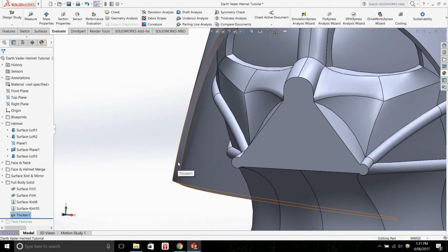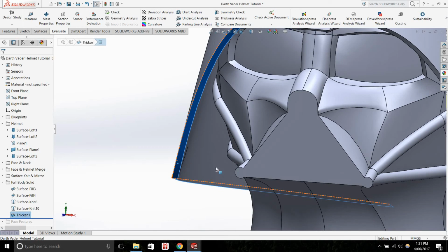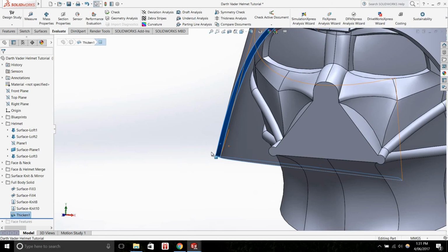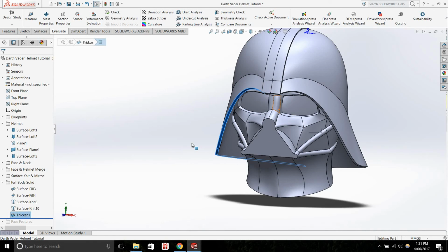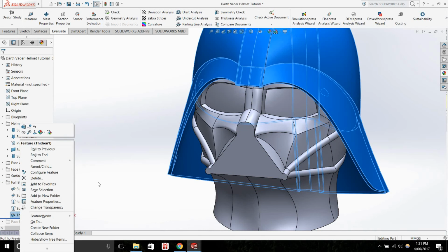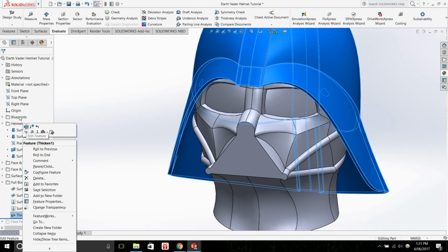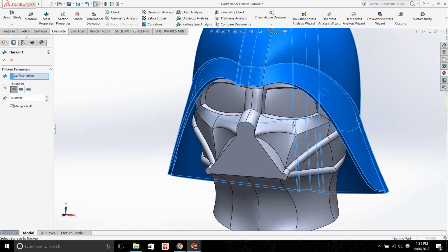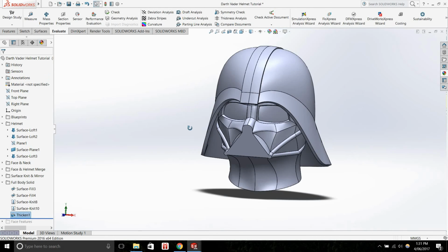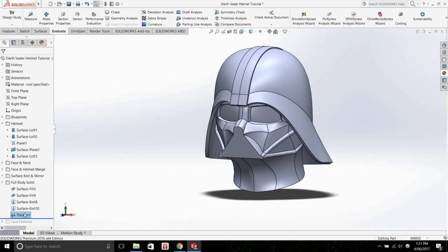The minimum thickness I can probably print is 1 to 2mm. So I made it 5mm so that if I print a quarter size, divided by 4, it should roughly be okay. But the good thing about parametric modeling, where you have a design history, is that I could go back in and make that 8 millimeters thickness, and it'll just rebuild like that.